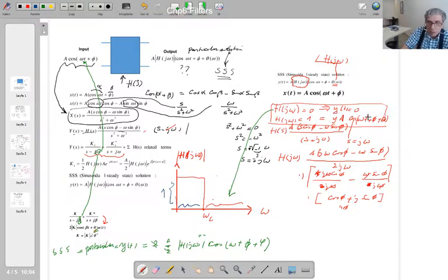That output is going to be in the same format as your input, isn't it? So that means sinusoidal functions whose frequency is within this range are going to be observed at the output, while the other frequency sinusoidal functions are not going to be seen. That means you made a filter, isn't it?